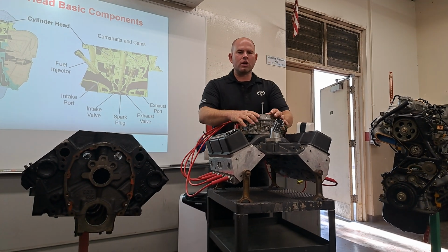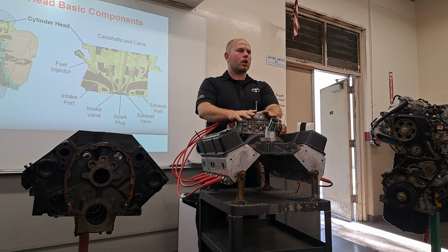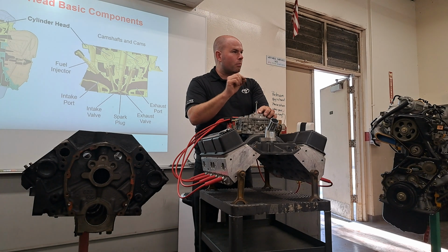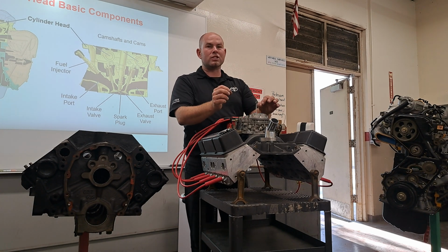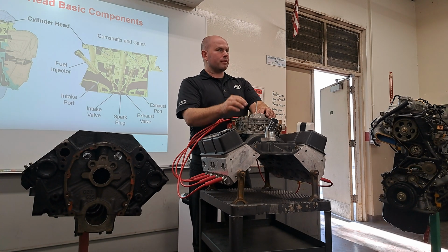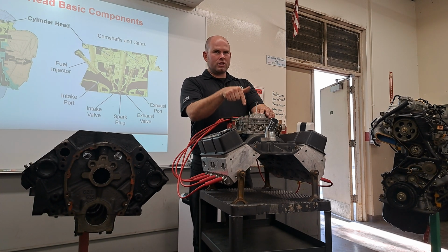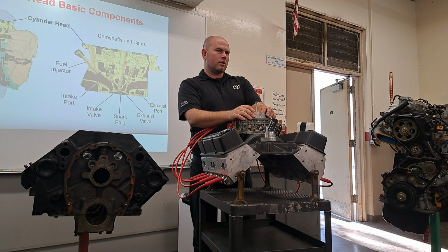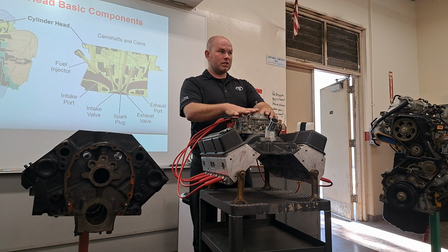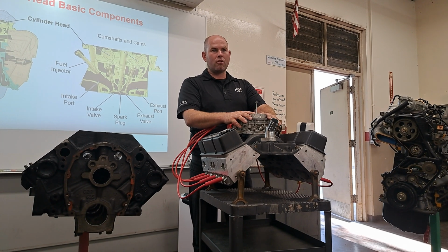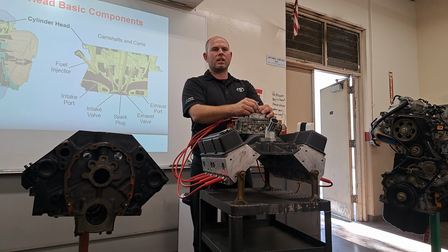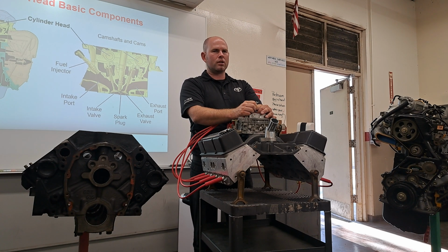You could adjust a lot of stuff on this carburetor because it was made to do that. The negative is there's a lot of little ports and passages and pieces and linkage and springs and stuff, so it's pretty common that it would need a little something. This has no ability to adjust for changes like altitude and temperature, so this might need constant little tweaks. Fuel injection is made so that you get in the car, you start the car, it looks at everything and it adjusts on the fly using the computer. So it makes a lot of sense.